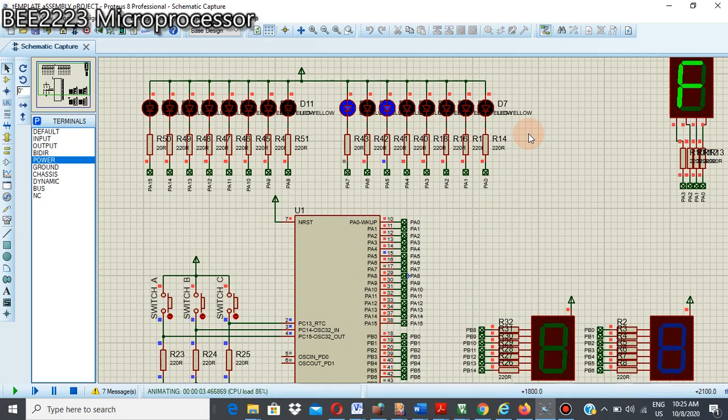Yeah. In this case, I've also connected a 7 segment. The 7 segment I also connect to port A0, port A1, 2, 3. That's why this 7 segment display is changing in line with these 4 LEDs. Okay, from F, here it is now 0 because all 0, 0, 0 represent 0. This one is a BCD, binary coded decimal 7 segment.